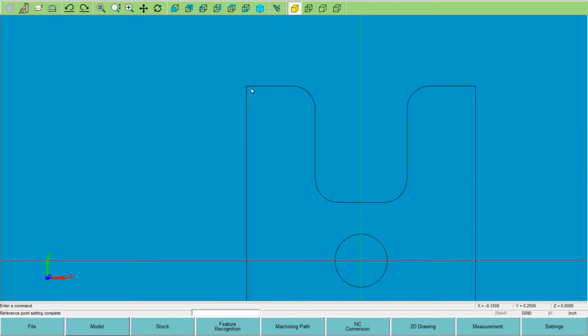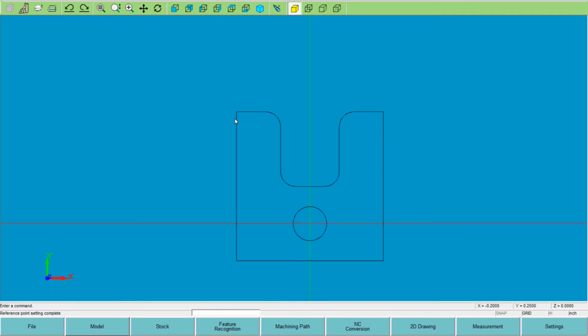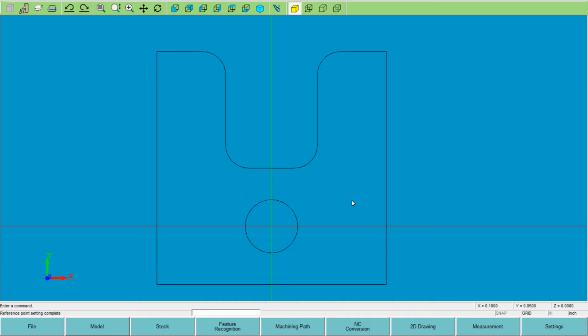Now, notice as a wire EDM programmer, we have the situation with sharp corners drawn in the geometry. Our wire machine cannot cut sharp corners on an inside. It can make sharp outside corners, but it cannot make sharp inside corners. So, something to consider if the two pieces you're trying to make, a punch and a die type fit together, all your corners should have some kind of radius if you want them to fit together, unless you have some huge amount of clearance between the two.